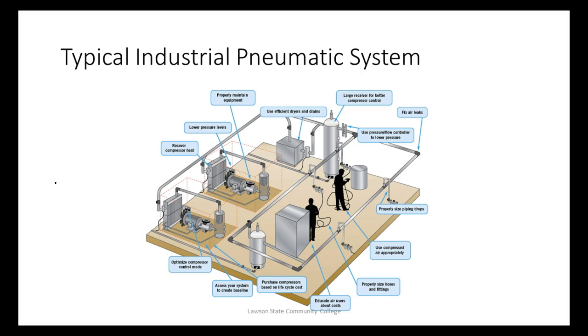So if you're in a hydraulic system that's got an accumulator on it, you're going to have to bleed that or disconnect or do something with that accumulator first. I don't know if they have those at Rose or not. It wouldn't surprise me if they didn't, because y'all got a lot of things down there that if power fails, you don't want things to open and fall on your hydraulics. And that's what the accumulator does. It maintains pressure even when the pump's not running.